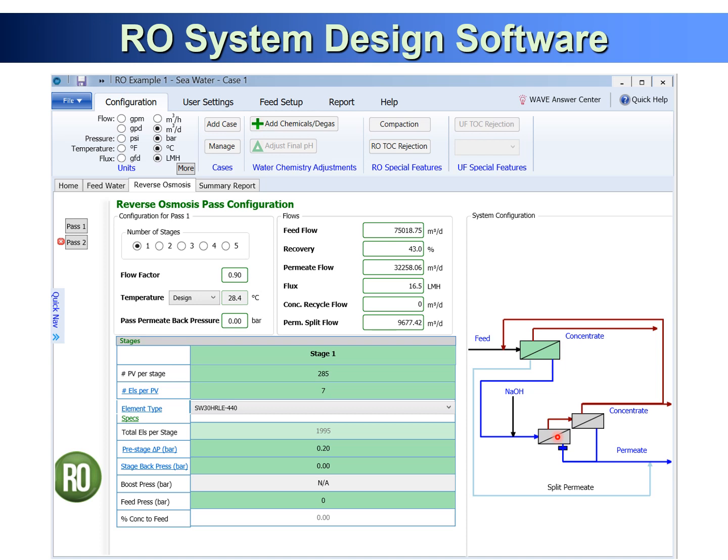So this is the second pass water, and then permeate following. And then the second pass concentrate can be mixed with the feed water again. So based on your permeate split flow and concentrate recycle flow, we can design your system configuration using this reverse osmosis step.